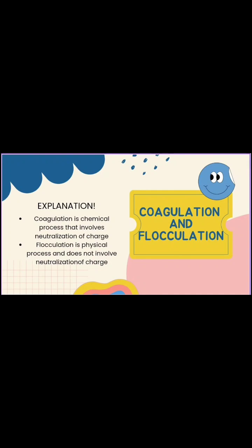This process commonly uses chemical coagulants such as aluminium sulfate to neutralize the particles electrically to make them sticky with each other so that they can coalesce and form large particles called floc. The charge neutralization is called coagulation and creating large floc from smaller particles is called flocculation.